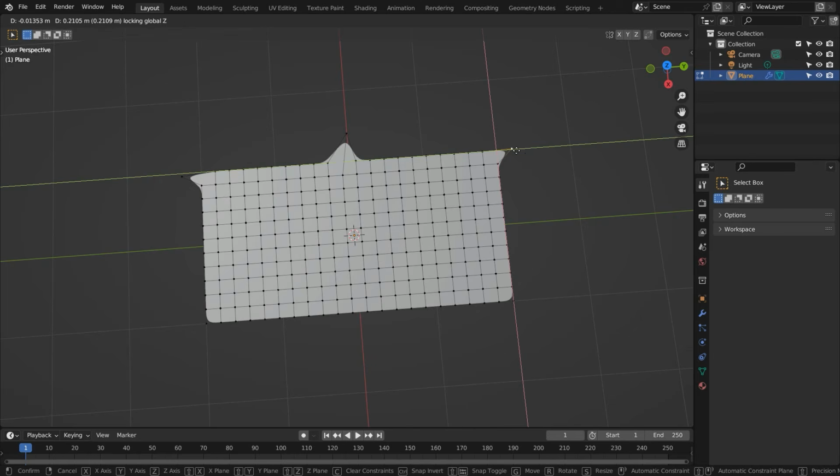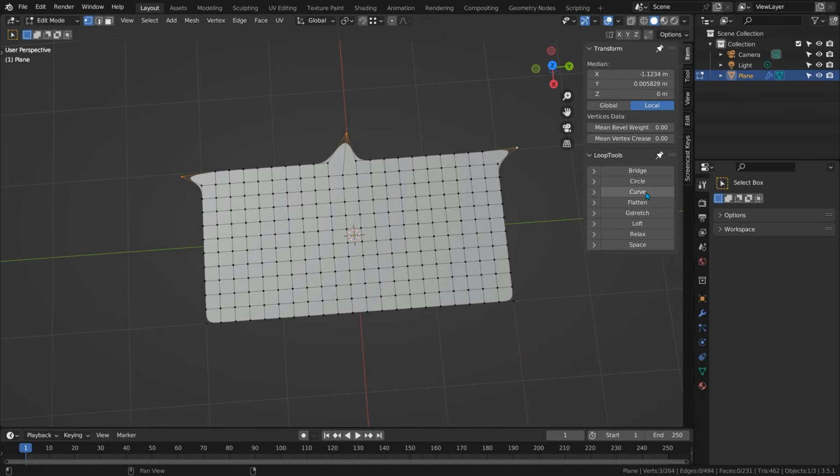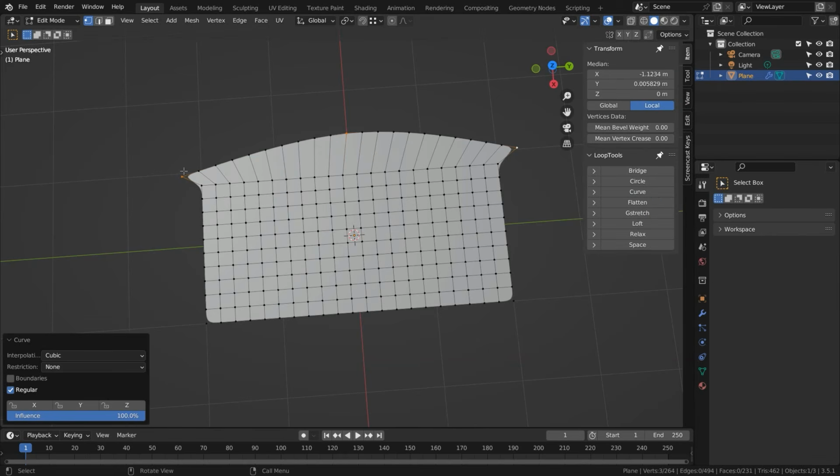And then I'll start using our curve tool again. I'll select the left corner point, then the center point that we moved, and then the right side corner point. Make sure the edit tab at the end panel is displayed and press curve. And that'll create the curve, which you just have to assume would match our blueprint or reference image. Then I might do the same along this edge.